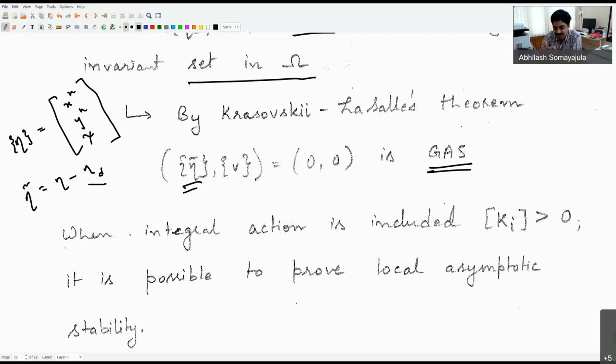Okay, next class we'll look at what to do if I want to place the poles of my multiple input, multiple output system. This MIMO system's poles, I want to place at a particular location. Pole placement for multiple input, multiple output systems, how to do that. And what we did as a formal algorithm for single input, single output systems, we'll try to derive a similar algorithm for our multiple input, multiple output system. Notice here that this controller is nonlinear. The plant is nonlinear, the controller also is nonlinear. Whereas in the linear, single input, single output case that we looked at, the plant was linear and the control system was also linear. Okay, so we'll try to see how to do that in the next lecture.